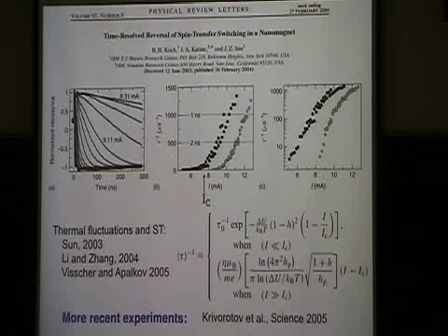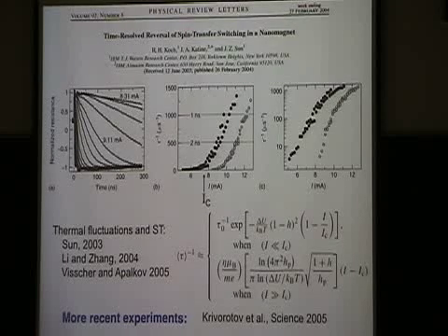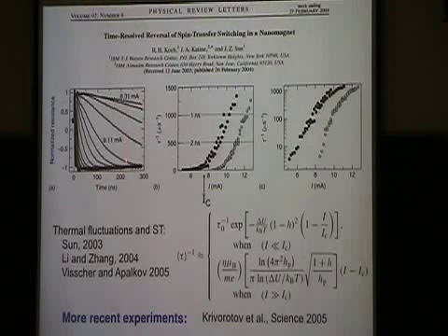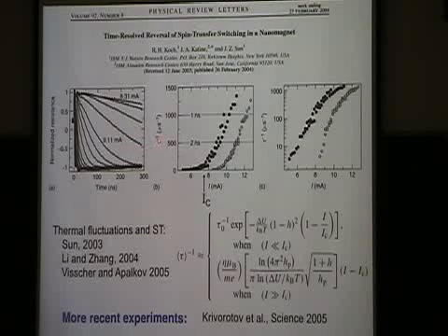Most experimentalists, if you told them you wanted to measure a 1% change in resistance, would say you have to have a very narrow bandwidth. You would use a lock-in amplifier. So these were averaged over many times. I would guess that this is not just noise in the measurement. That would be my first guess.